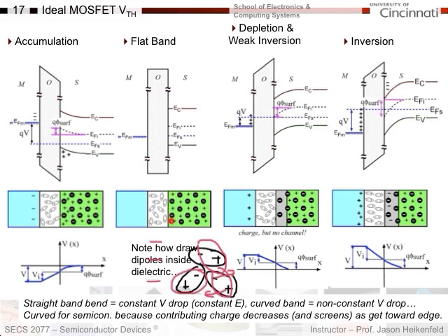And so if a dielectric has a very high dielectric constant, high permittivity, then that means its ability to reorient charge like this and transfer charge across is much greater than a typical material. So let's look at accumulation here. Here's accumulation. I basically put negative voltage here.